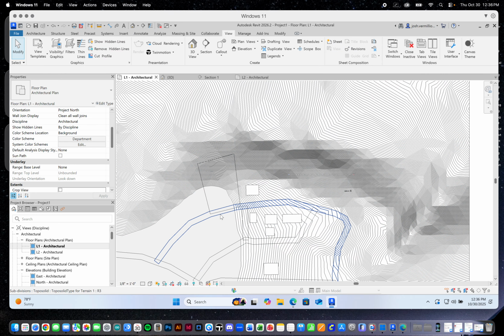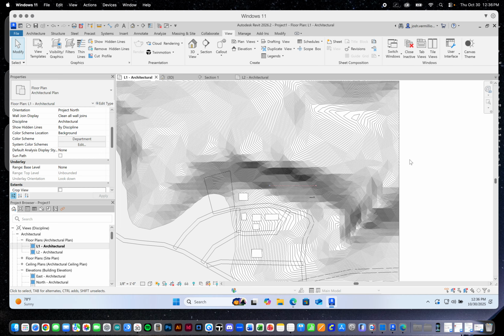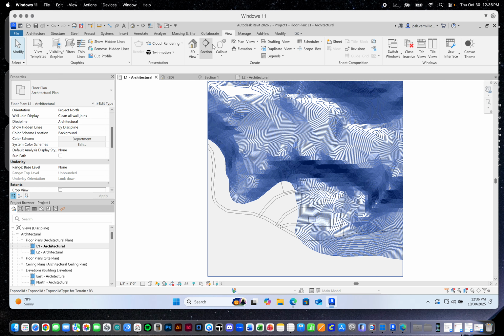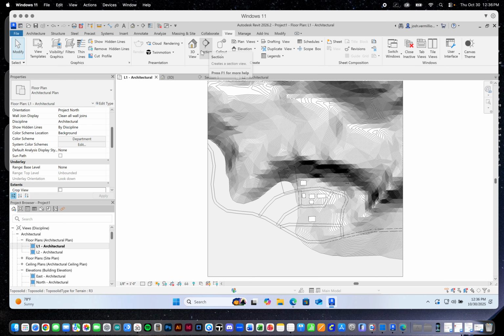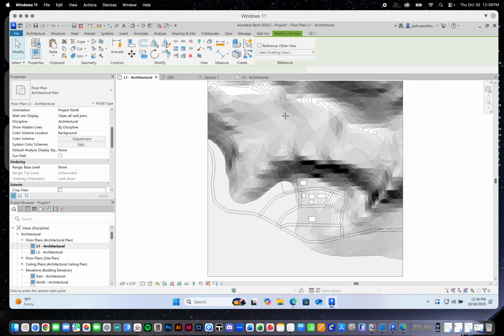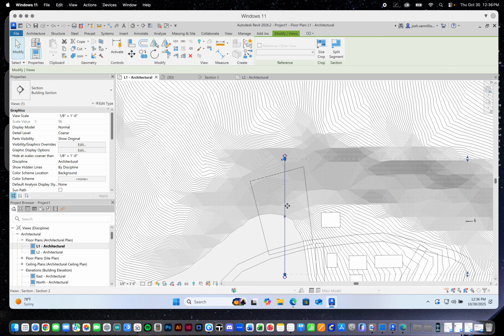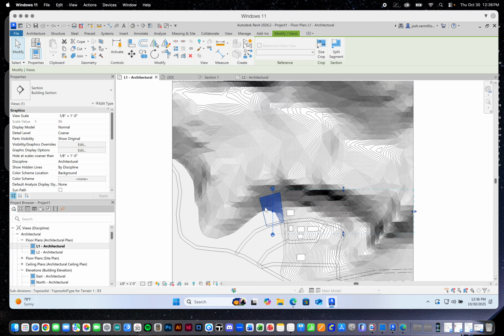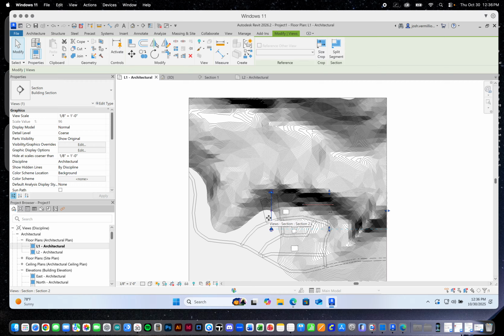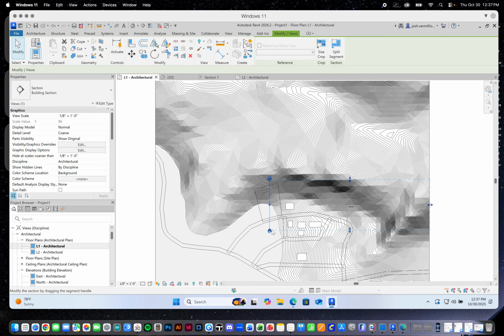site. All right. In order to create a new section drawing, I go to one of the plans, and then I go to the View tab up here and find the little section tool, which creates a section view. Now I can draw a section marker, north-south, through my site. I want to make sure that's true north-south. We're going to go with the sun and cardinal north-south rather than any arbitrary adjustment for the road. We're going to actually set back from the road and have a bridge that connects things up. So just to let you know that.